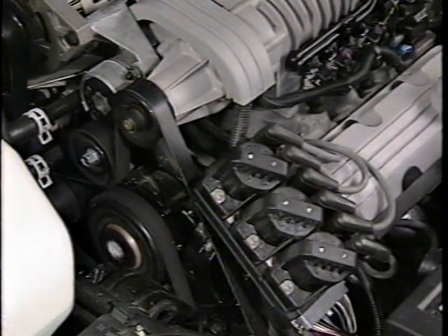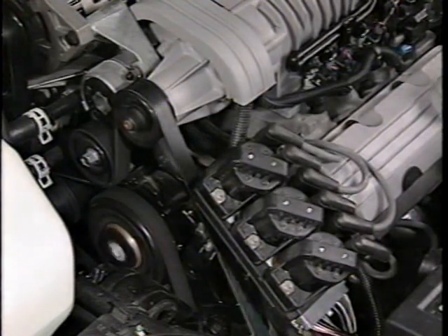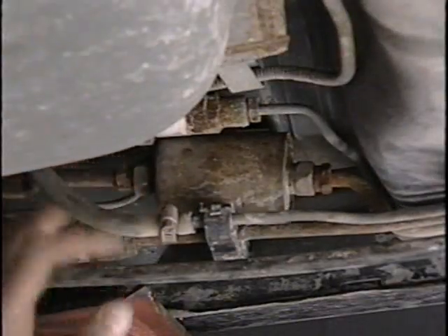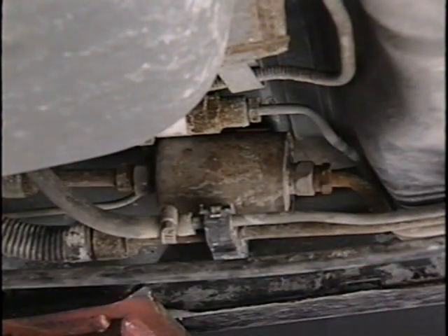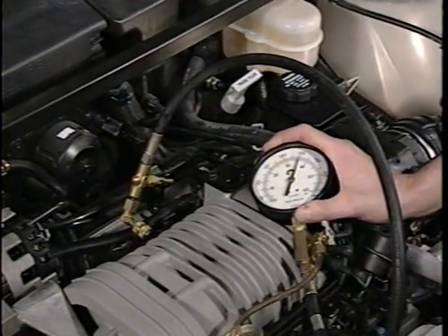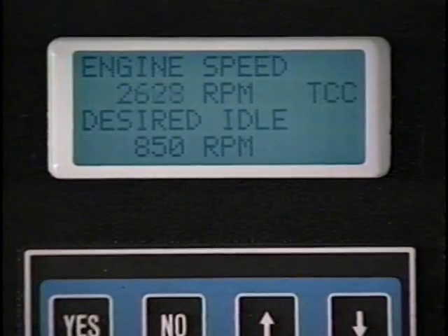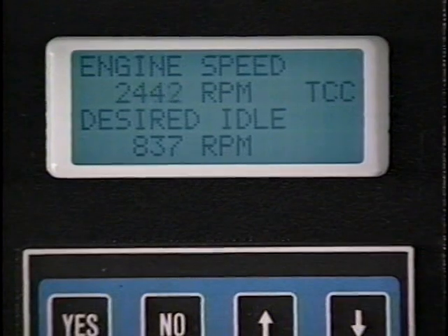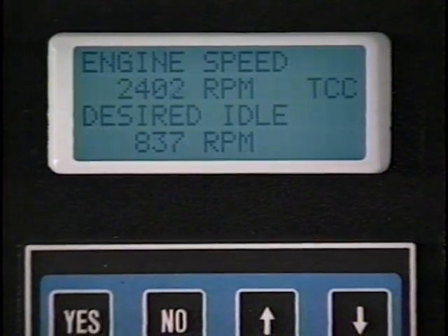all-inclusive. Not all possible causes can be listed under each and every symptom. For example, a restricted fuel filter could conceivably cause a rough idle, but a restricted fuel filter is not listed as a check for a rough idle, because a restricted fuel filter should first cause a loss of fuel pressure at higher engine speeds. Loss of fuel pressure should cause hot hesitation sag or low power complaints, along with the rough idle complaint.